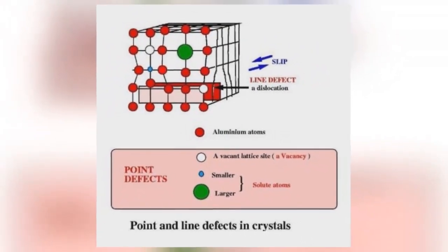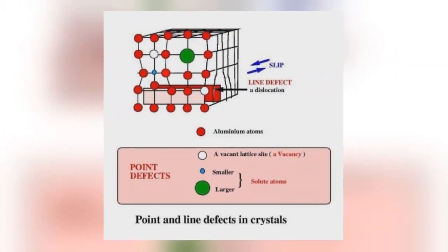These foreign atoms are known as solute atoms. They have atom sizes that are different from the atom size of aluminium. This means that solute atoms introduce a distortion into the aluminium lattice. It is a feature that has a controlling influence on how the alloy responds to heat treatment and to mechanical working.